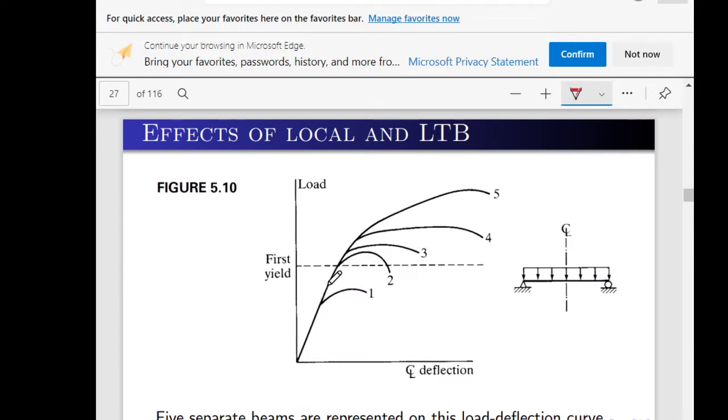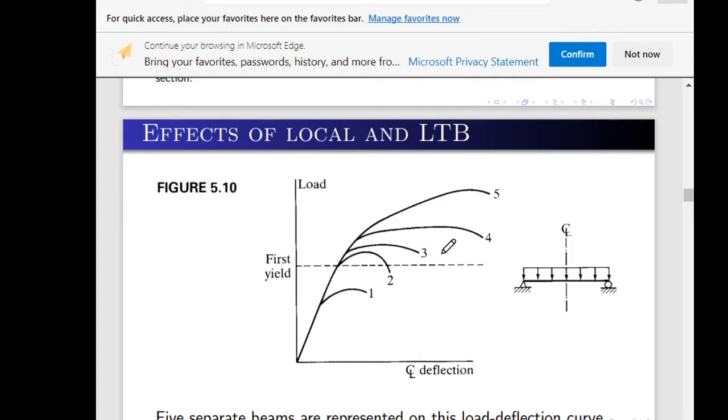There is this elastic limit, proportional limit, then it reaches the point of maximum yielding. Then as you remember in the behavior of steel, there is this elastic limit or proportional limit, then comes a time when it reaches its yielding strength or point, then it becomes somewhat horizontal, then it goes up again, gaining strength until it reaches its ultimate strength, then rupture.